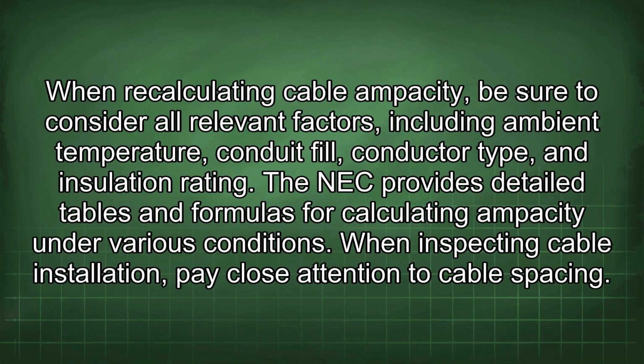When recalculating cable ampacity, be sure to consider all relevant factors, including ambient temperature, conduit fill, conductor type, and insulation rating. The NEC provides detailed tables and formulas for calculating ampacity under various conditions.